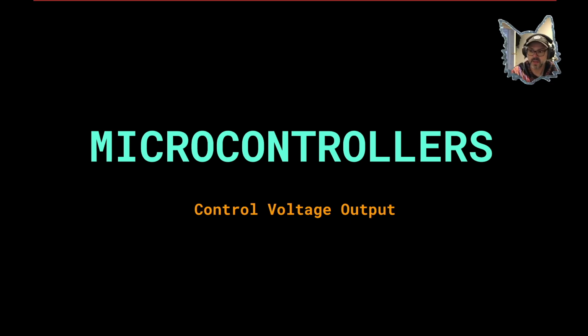All right, I also want to talk about another way of generating an analog signal from a microcontroller, and that is by utilizing pulse width modulation. By passing it through a low pass filter, we can smooth that out and get a fairly smooth analog signal out of it. And lastly, since today we are talking about control signals, we're just going to look at a simple way of generating a sine wave signal in code and then run it through our oscilloscope to look at this wave. All right, let's get started.